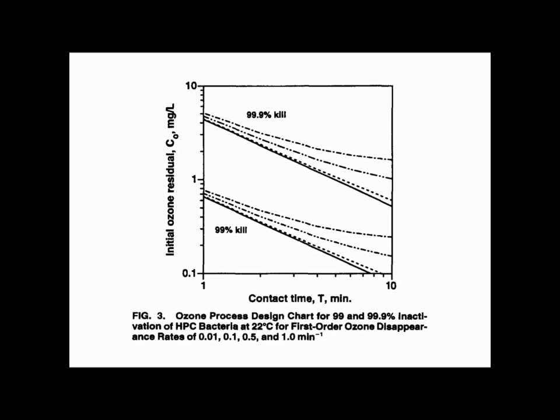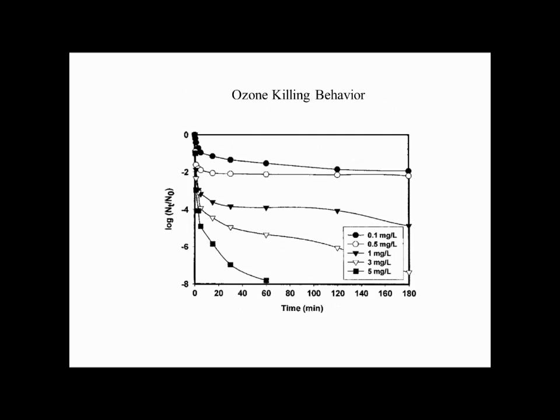So there are a lot of people that are using ozone, and a lot of people who misunderstand ozone, but what it shows here very clearly is the ozone that you make usually isn't around 10 minutes later. So in the sense of ozonating water to clean a tank, I want you to realize after 10 minutes you have no ozone left. The water is sterile, you sterilized it, but it's not a solution which is going to sterilize your tank because there's no ozone left. Okay? And this is the killing kinetics now. So here's the log of the number of cells that are viable versus the initial, and across time on the linear scale on the bottom for different levels of ozone.